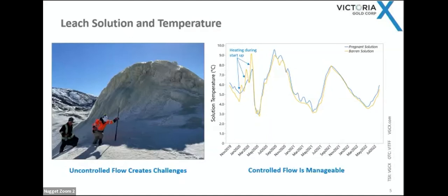That's an ice castle on top of the heap, okay? I've seen ice castles on heaps before, but nothing prepared me for the ones I saw this year. So you can see the shape of it is nice, good arc. And that came from an uncontrolled drip line that was allowed to spray. So you can imagine what that would do if we had the whole heap that way.